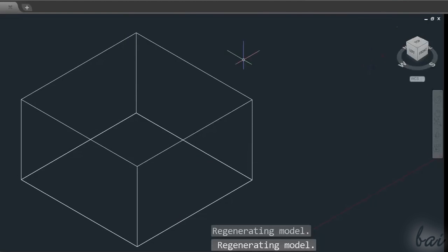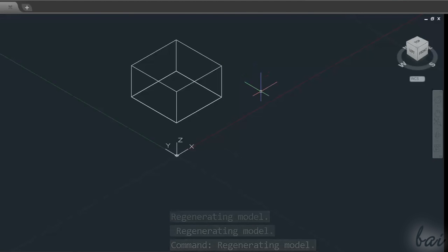To start making a 3D project, switch to a 3D environment clicking on one of the 3D view cube vertices. You will see the gizmo system and your pointer showing an additional blue axis, called z-axis, used to represent the 3D object's height, while the x and the y axes do fix the ground plane of your workspace.